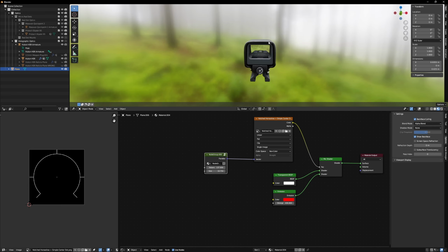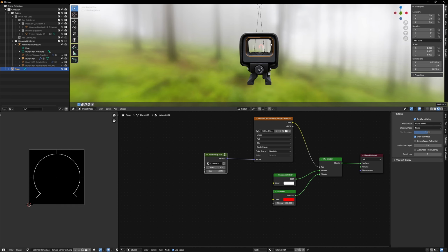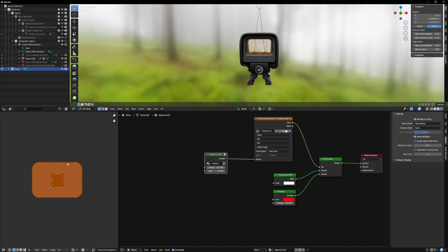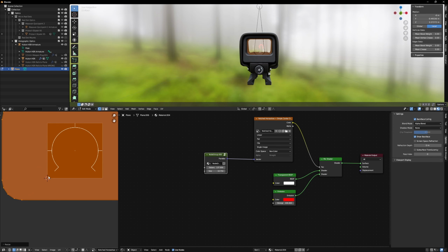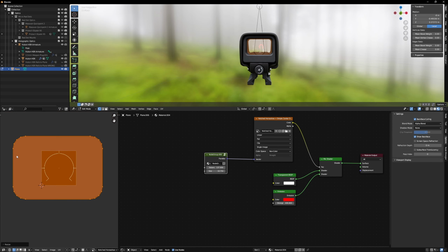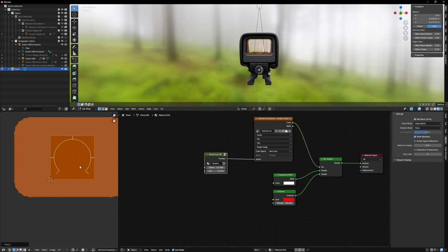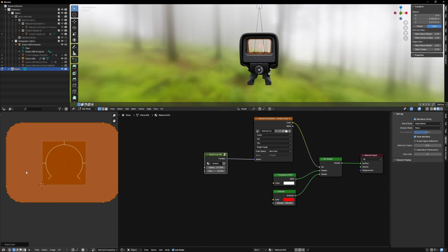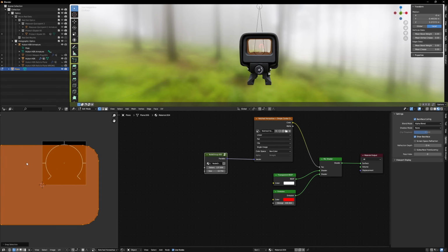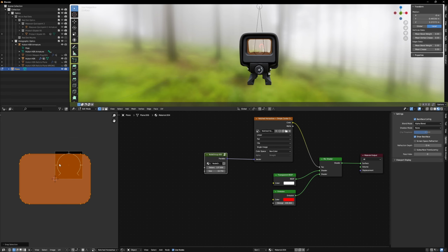One more important thing, you're not quite done yet. We're going to want to go into edit mode for this mesh. It's pretty important that you position this UV precisely. You want the origin point to be in the direct center of this UV. Your cursor is probably already at the origin because that's where it is by default, but we're just going to hit Shift S and do cursor to origin to ensure that it is there. And then with everything selected, we're going to Shift S again and do selected to cursor (with offset). And that's going to do exactly what we want, which is put that in the center.